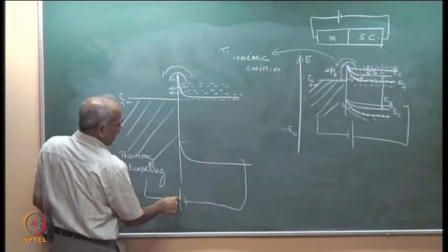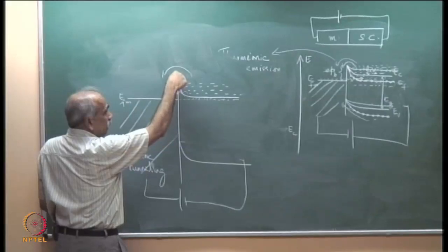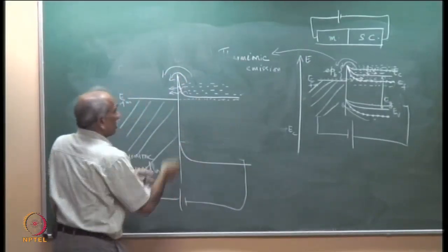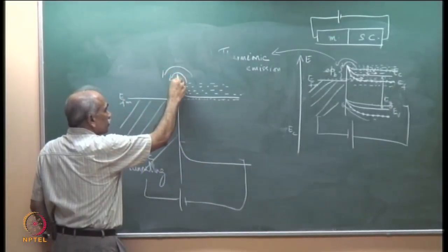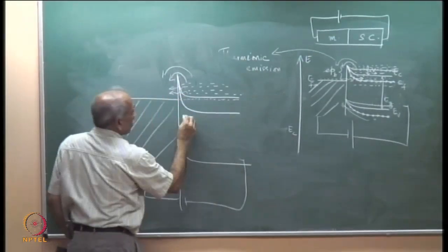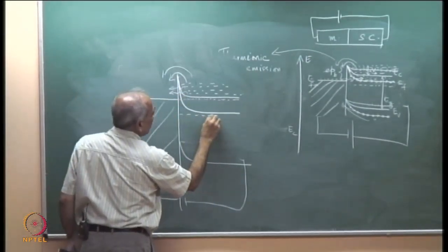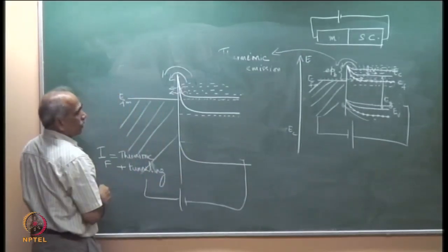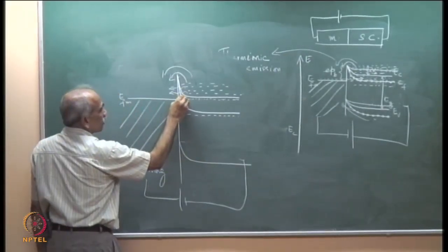If you reverse bias this, which means to this N side you apply positive, this band will come down further. So, let me draw in the same diagram. There is a difference in the Fermi levels now. EF has separated out. So, this is reverse biasing.